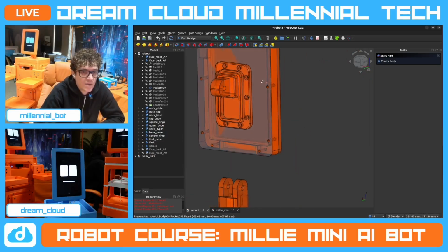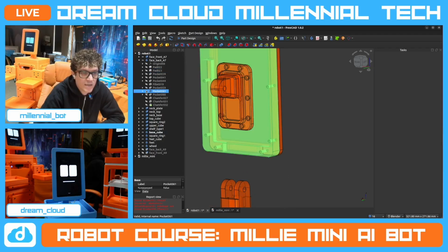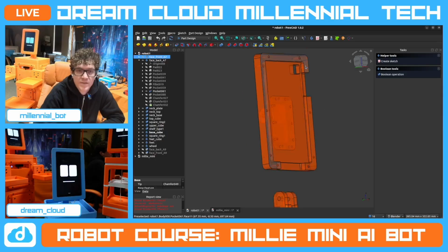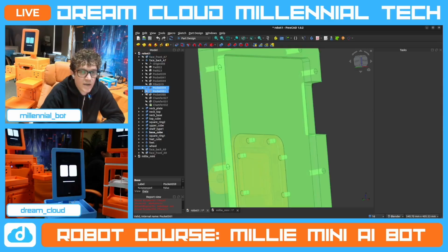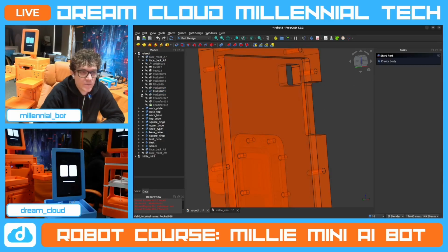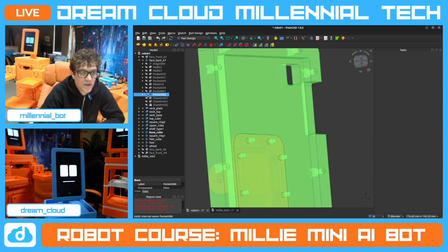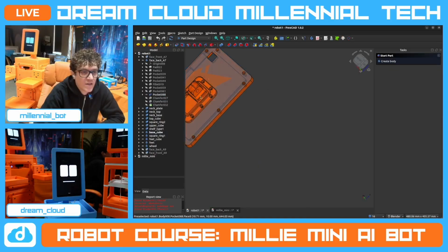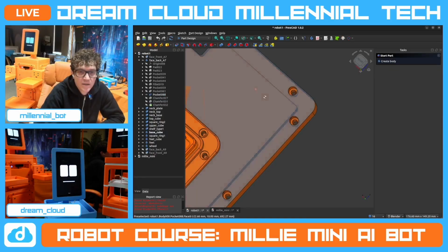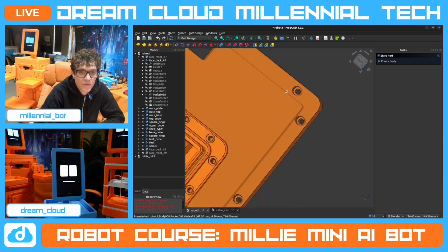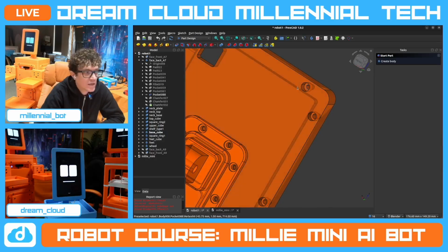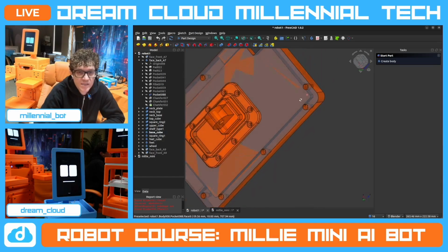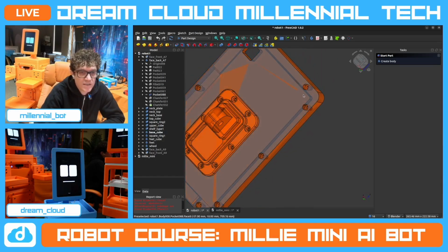And then just to clean this up more, let's see what other pockets are here. Oh, this guy right here. So then I needed to make a pocket for the camera to be able to see through the back camera, which I measured, and we're going to do all that. And then you do another pocket on top of that pocket that allows you to get to that hole, so that basically these screws are sunken in here, and that's where the washer goes. So you have two different radiuses of hole that are working together.